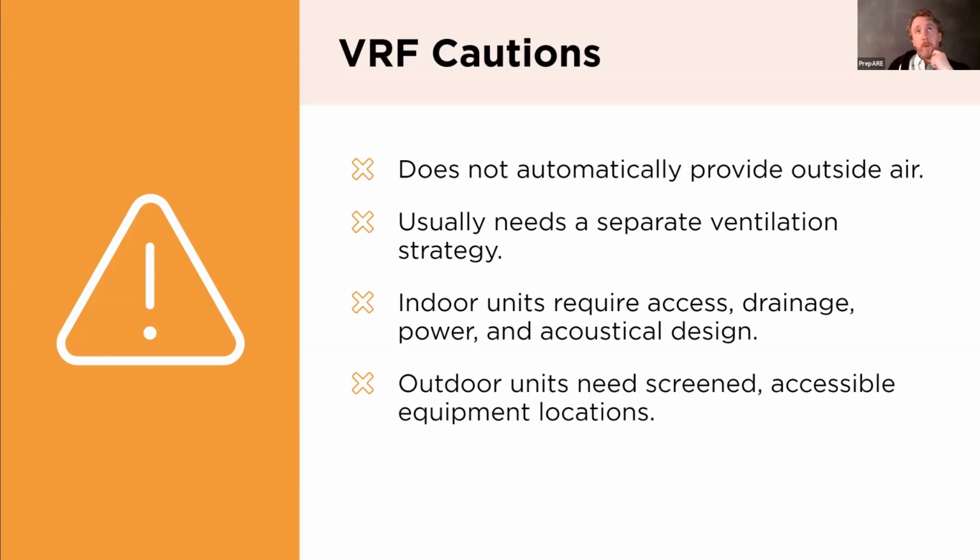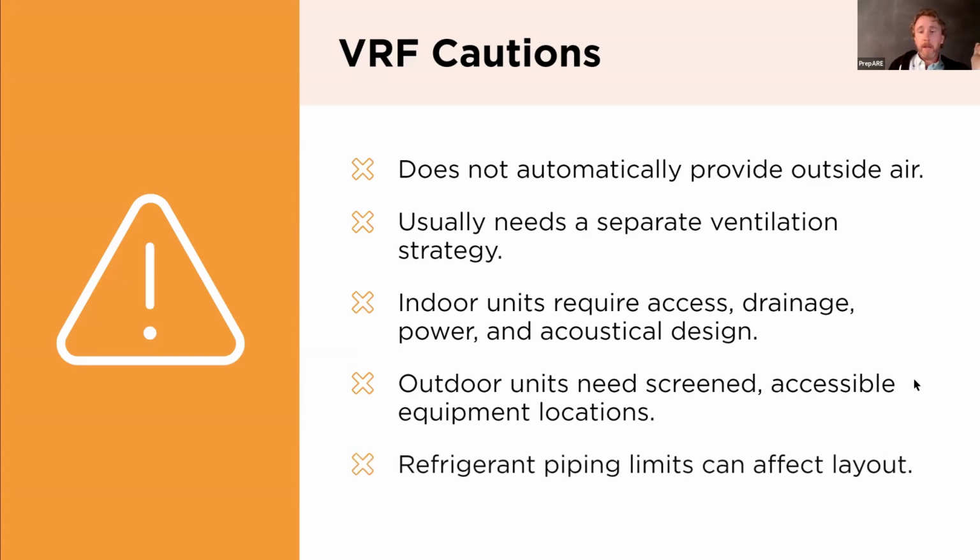should it need it in acoustically sensitive areas. If you have outdoor units, they may need to be screened and considered for maintenance access. And of course, your refrigerant piping limits can affect your layout, but it's not generally a big concern. It just may have a limit to how far it can go, and you may need to do multiple systems if it's a really, really large building.